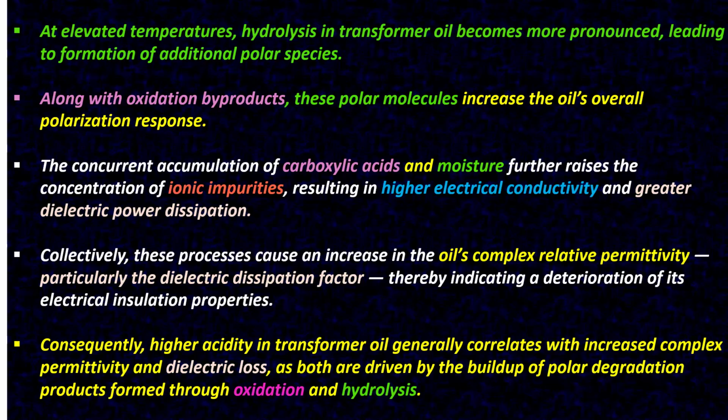Collectively, these processes cause an increase in the oil's complex relative permittivity, particularly the dielectric dissipation factor, thereby indicating a deterioration of its electrical insulation properties.